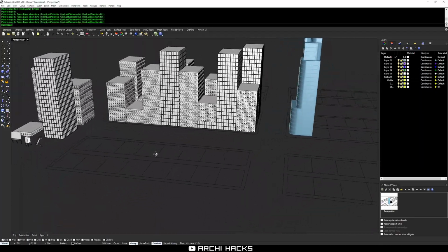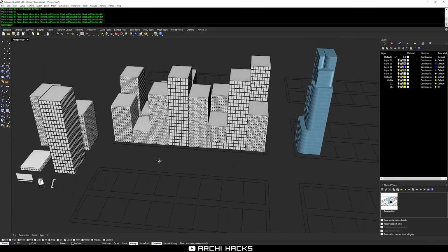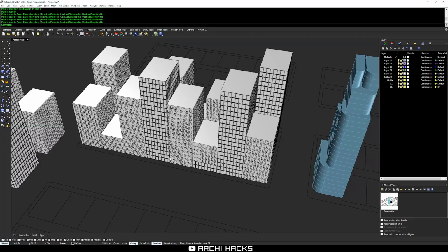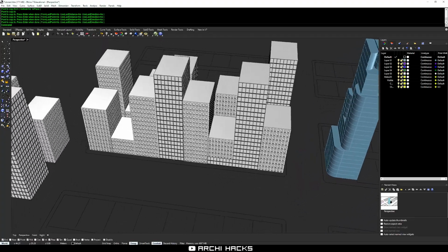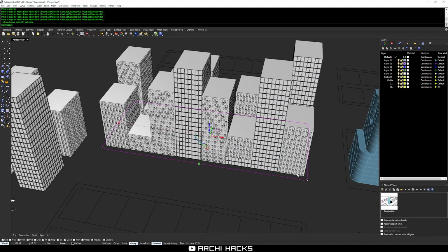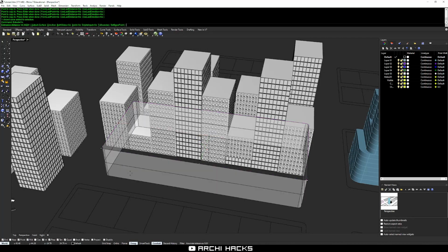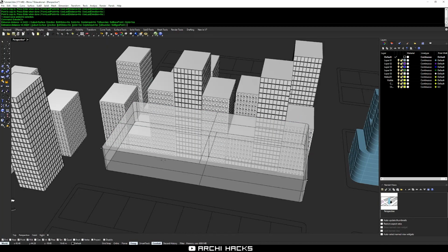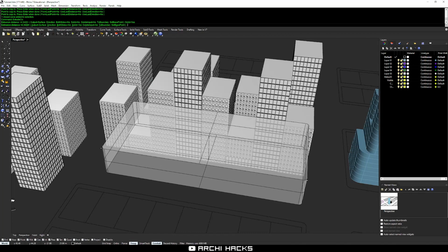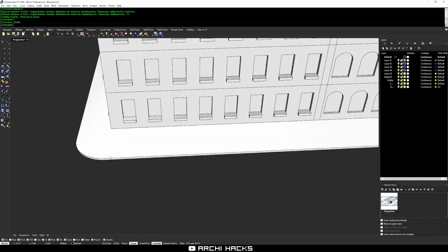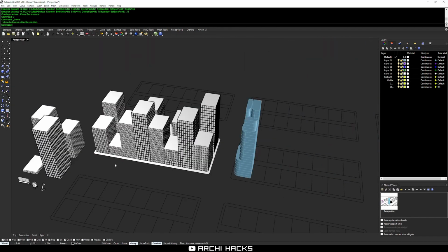Okay, cool. So now we have a pretty decent looking, a little bit cartoonish, but this gives you a very conceptual look, so it's actually nice on its own. Now I'm going to extrude this outline of the block downwards. I'm going to make sure this is a solid piece by clicking over here. And I'm going to type in 0.15 for the height of the sidewalk. Okay, so that gave it a little bit of thickness.